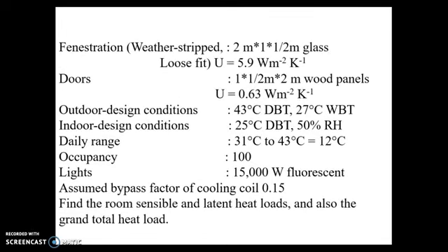The fenestration, they gave the fenestration size and the heat transfer coefficient at the windows, U equal to 5.9 watt per meter square Kelvin, and they gave the door size, and the overall heat transfer coefficient of the air at the door is 0.63 watt per meter square Kelvin.